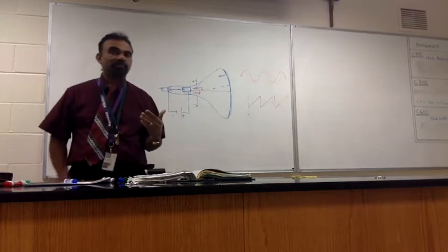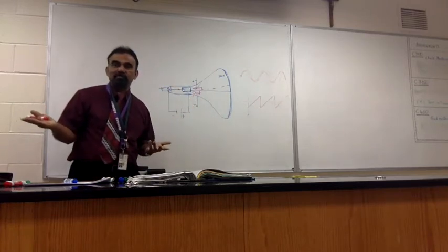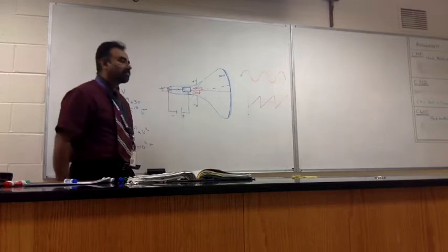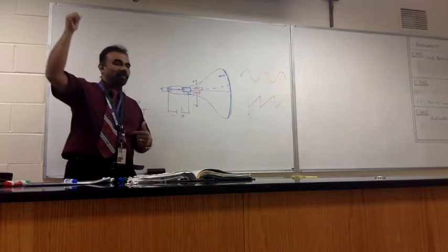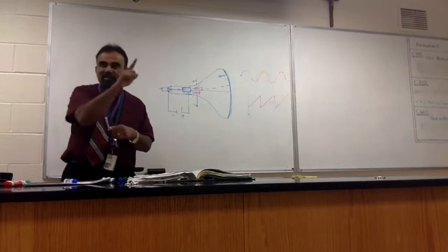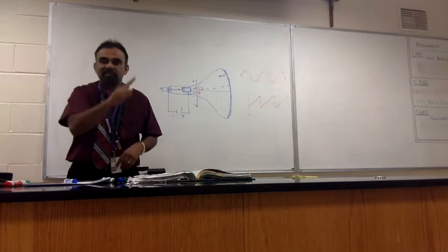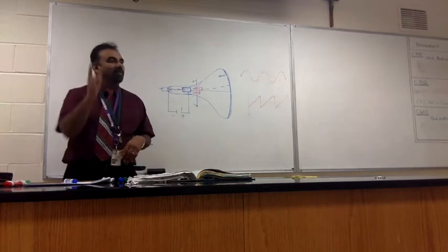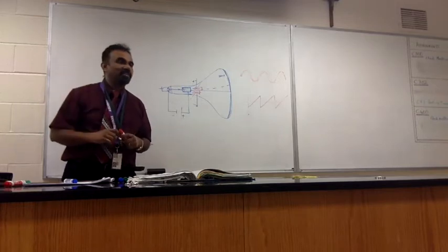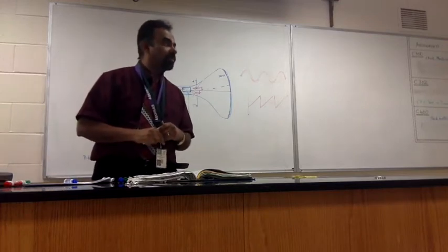And a cathode ray tube is the kind of tube that we use in a television also. Okay? In a television, instead of these plates, they use magnetic coils. And the signal that is coming from the television antenna is fed over there. And so it is creating lots of spots on the screen. It scans like that multiple times. And when it scans multiple times, it is creating spots of different intensities at different spots, and then it creates an image. So it's a lot more going on a screen than you can imagine.